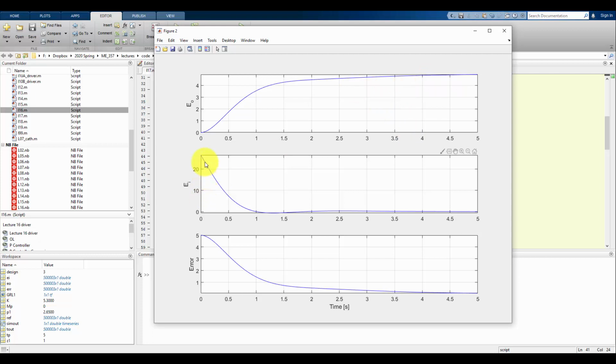Our input effort is, the maximum is less. We'll find out what its value is in a second here. But it's not performing like the first 2 designs, and oftentimes we don't want our closed loop system to perform without that overshoot. Now, maybe this is a design we're interested in, so it's worth looking at, but probably we wouldn't go with this design. And this odd behavior that's different than what we saw before is due to that extra 0, that 0 and third pole actually being to the right of the real part of the dominant poles.